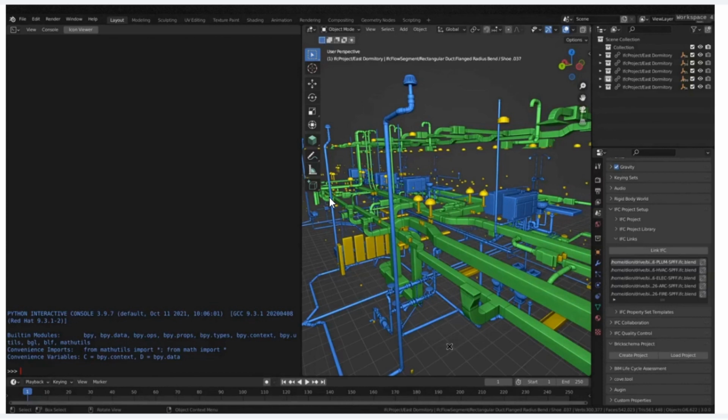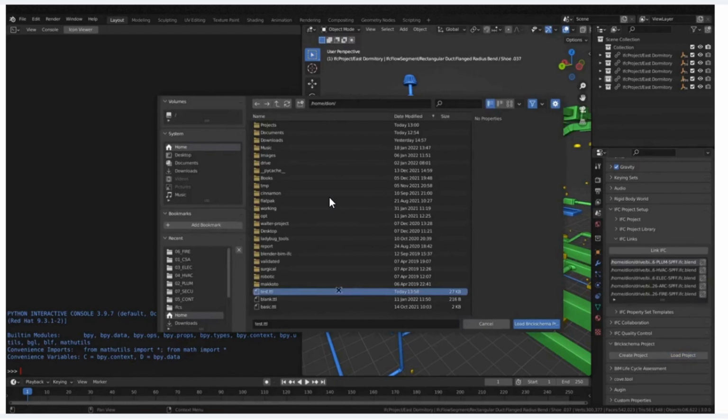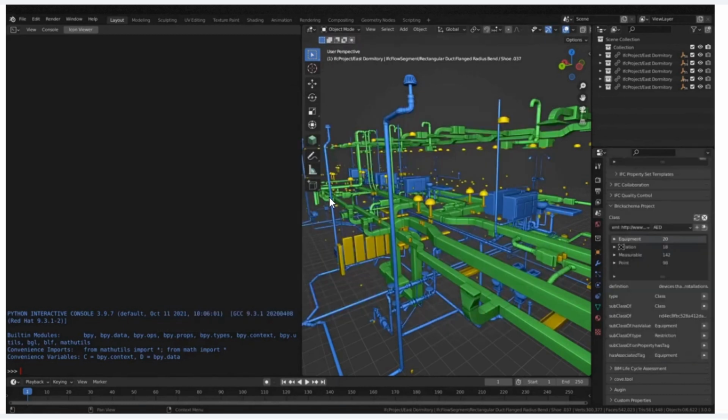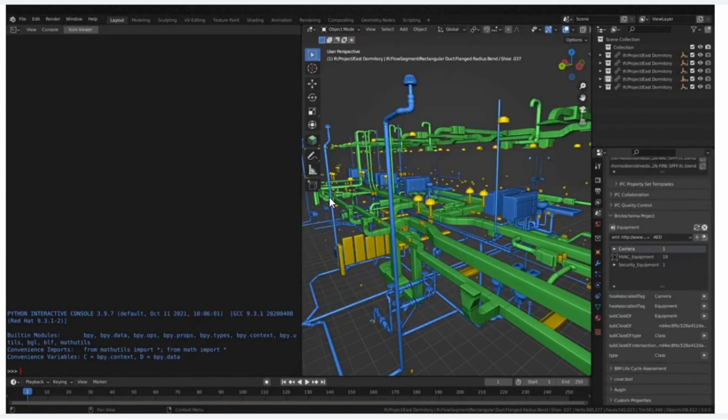Sometimes your real estate developer will market something called a digital twin of your building. That sounds really advanced, but it's basically a BIM model that has live sensor data connected. The high-level description of your building systems are usually both described in IFC in your BIM model and sometimes in something called Brick schema. To view a Brick schema model, just load the project down here. And inside equipment, you can see all of our smart devices.